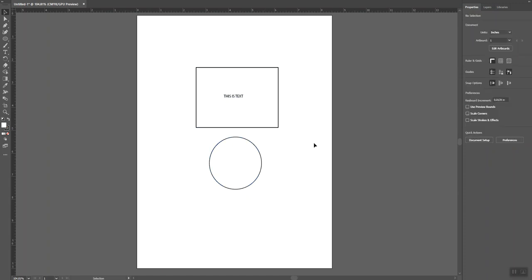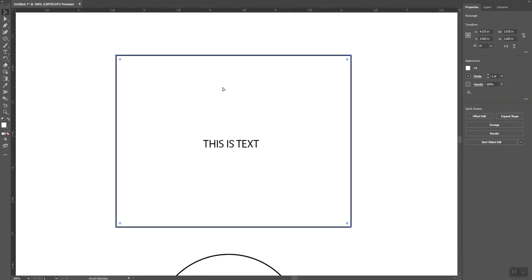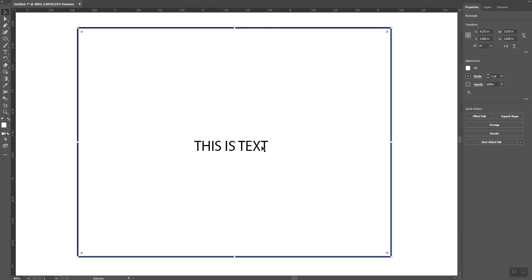So let's just say, for example, that we wanted to cut this rectangle out, and cut this circle out, and we wanted to engrave, just say this is a gift or a cutting board, for example. You wanted to engrave this. So basically there's two functions the laser cutter does. It'll cut an outline along a line like this. This is called a vector. It'll cut it out with the laser. And the other thing it does is it will engrave. So basically it will go back and forth with the laser to do what's called rasterization or rastering, engrave.